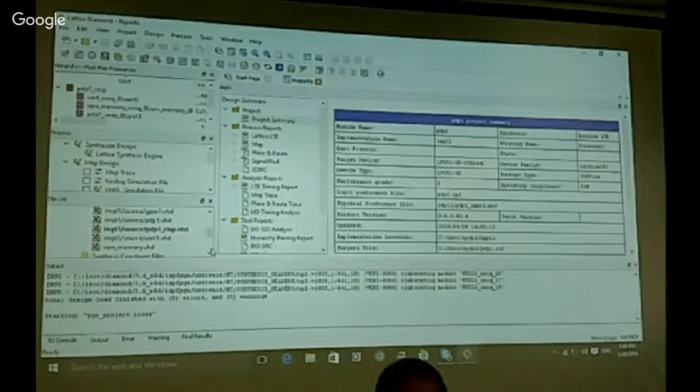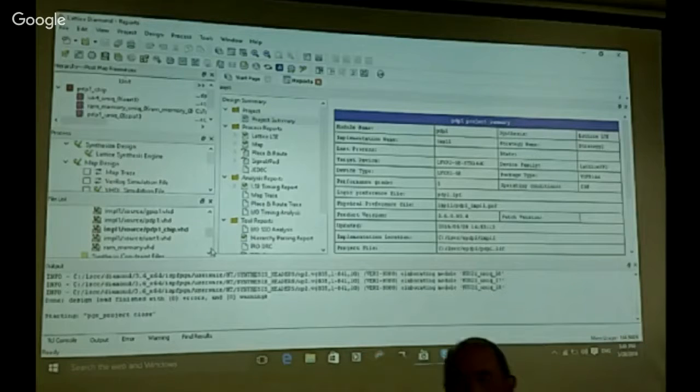So I deviate from this too, and then the indirection bit. If the indirect bit in the instruction is set to 1, then the memory does not provide just the data; it provides an address. So you have to go fetch the content of that address.